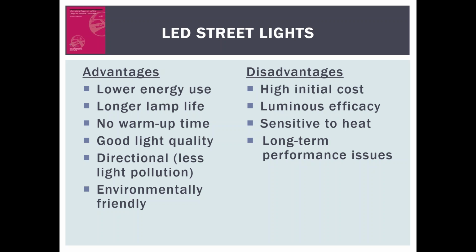And by the way, I checked with some of my colleagues involved in some of the street light design projects and asked for some ballpark lighting costs for LED lights. I was told that for roadway lighting, and the cost, by the way, can vary based on part of the design of the pole, how the pole is installed, and a number of other factors. But for a typical LED roadway lighting, when you have 2 lamps per pole, expect a cost of about $5,000 to $7,000 per pole. For pedestrian level lighting, expect closer to about $3,000 to $5,000 per pole.